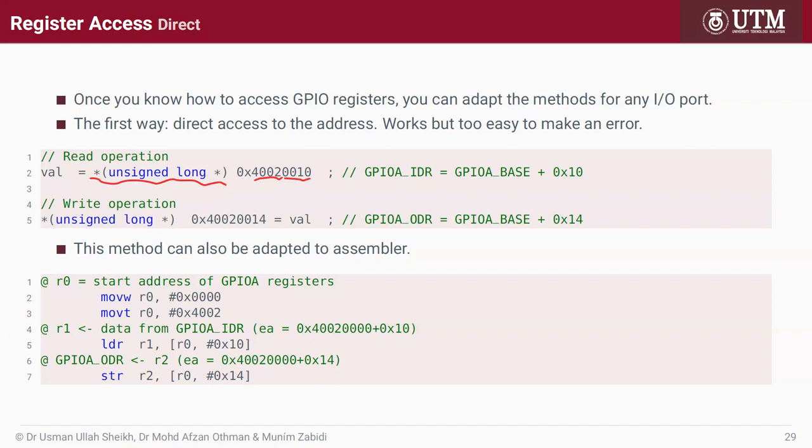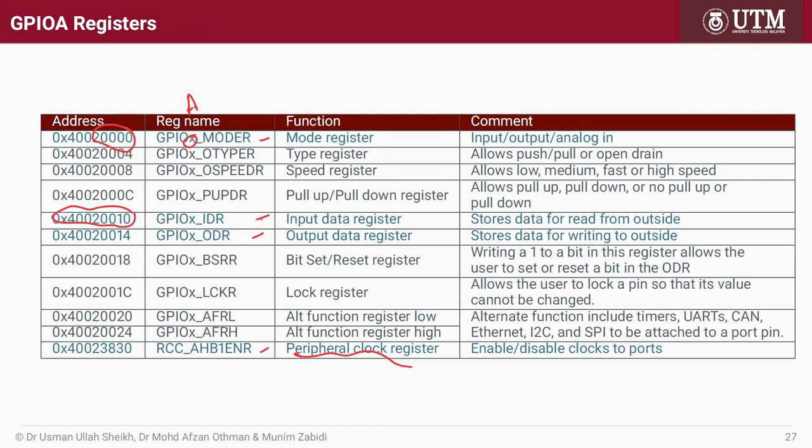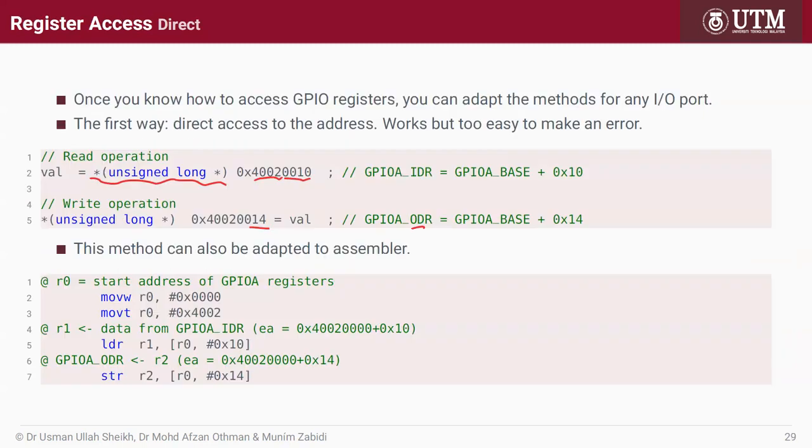So then if I want to write, I cannot use the same register. I have to use the ODR register, different address. So different address. I'll refer back here, make sure. Go back here, make sure same number. Copy that number, put it here.